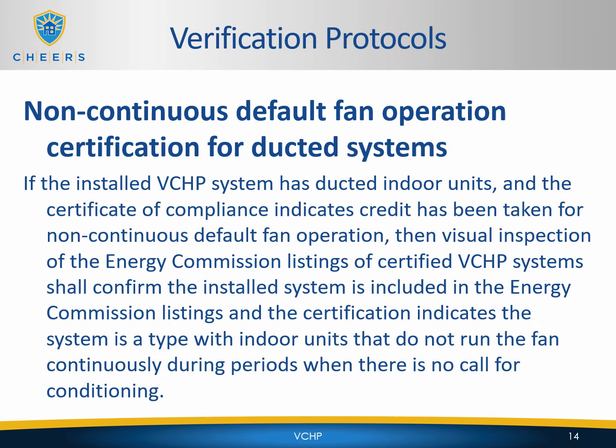If the installed VCHP system has ducted indoor units and the certificate of compliance indicates credit has been taken for non-continuous default fan operation, then visual inspection of the Energy Commission listings of certified VCHP systems shall confirm the installed system is included in the Energy Commission listings and the certification indicates the system is a type with indoor units that do not run the fan continuously during periods when there is no call for conditioning.